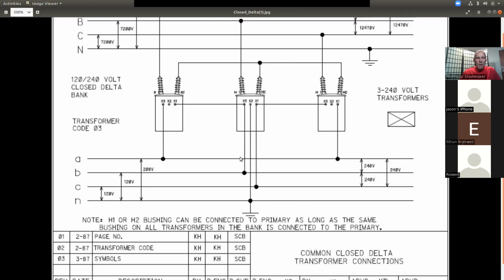You just have to know in all of these drawings where you put the high leg at or where you put the power leg at. That will change your voltage output. So you notice 120, 120, that's off the lighting transformer, but my power leg is attaching to A. So that's 120 times 1.7325.